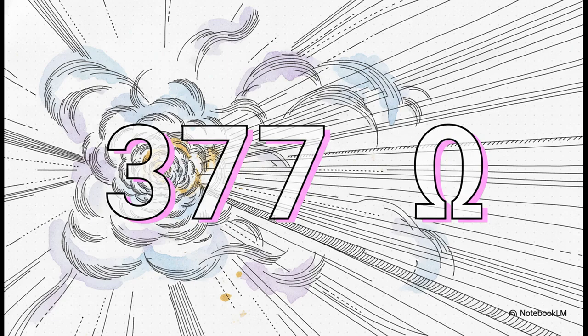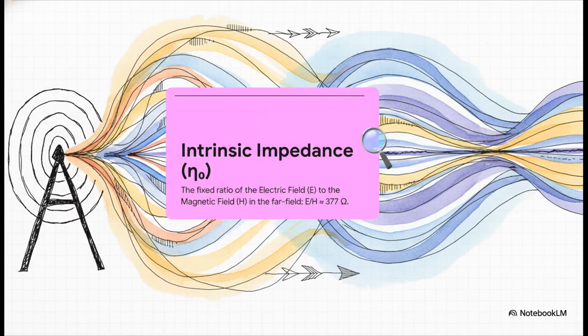And in this far field, there's one magic number that governs the relationship between the E and H fields: 377 ohms. This is what we call the intrinsic impedance of free space. It's the fixed, constant ratio of the electric field strength to the magnetic field strength. The fact that E divided by H is always 377 ohms out here tells us the wave is finally stable and is efficiently carrying energy away from the antenna forever.